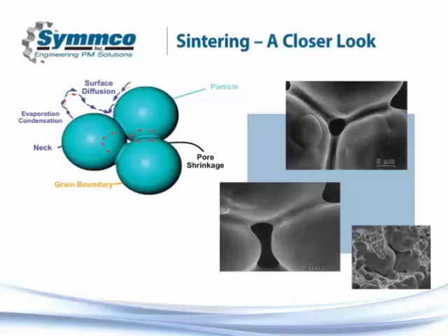One last real quick thing on this slide directly related to the PM101 side is we do have porosity. Compaction densities in iron-based materials are typically around 6.8 grams per cubic centimeter, up to maybe as high as 7.3 grams per cubic centimeter.